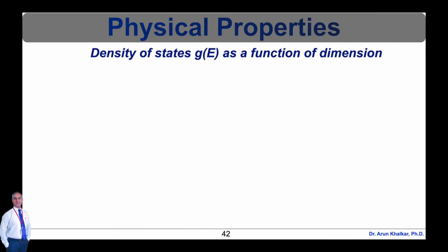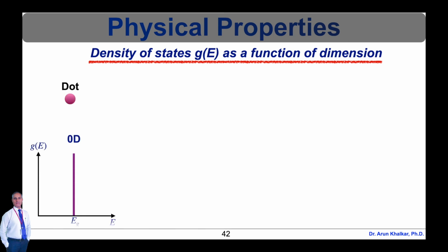In physical properties, the classification according to the number of reduced dimensions usually refers to the degrees of freedom, that is DOF, in the momentum. The density of states in bulk, that is 3D, 2D, 1D and 0-dimension semiconductor structure is shown in this diagram. 0-dimension structures have very well-defined and quantized energy levels. The quantum confinement effect corresponding to the size of the nanostructure can be estimated via a simple effective mass approximation model. Systems in which carriers are confined in all directions have no free carriers.